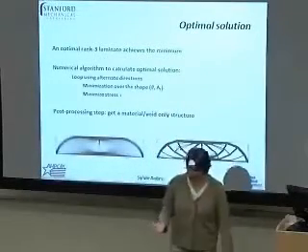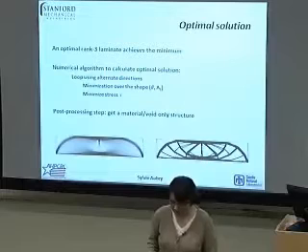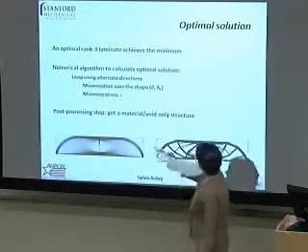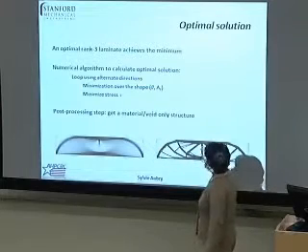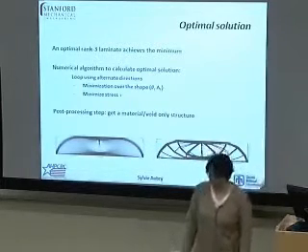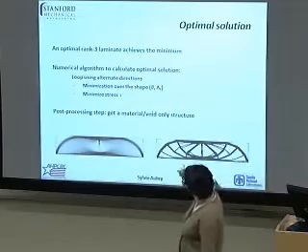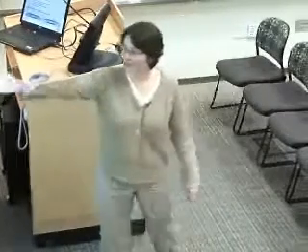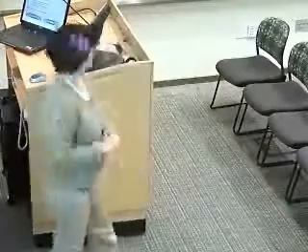And then you have this post-processing step that I was talking about, where you transform this optimal shape into this material-void-only structure. And the way you do that is that you play with that proportion theta. For instance, if theta is greater than 0.5, you say it's going to be material. If theta is lower than 0.5, you're going to have void. And again, you iterate like that, and you get some kind of not optimal, but close to optimal structure.